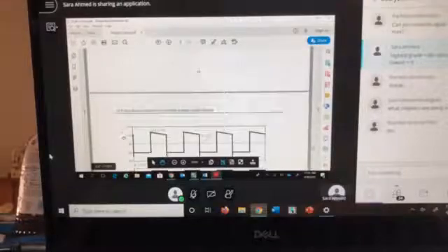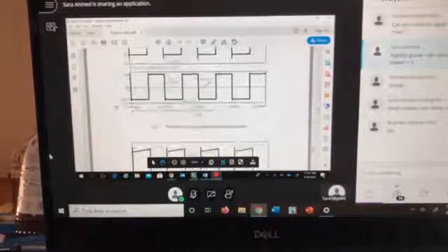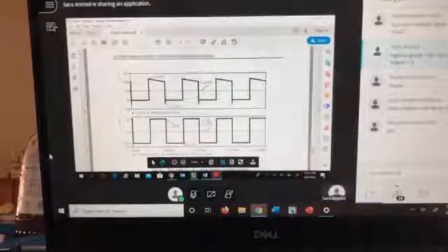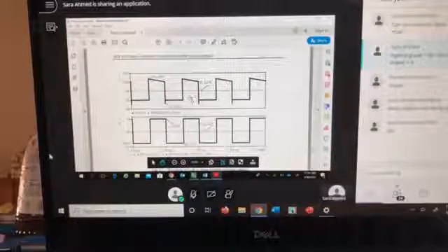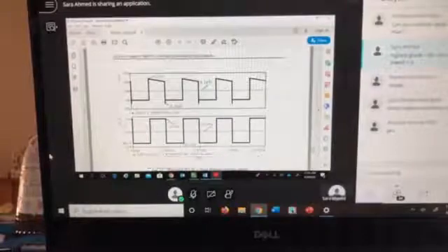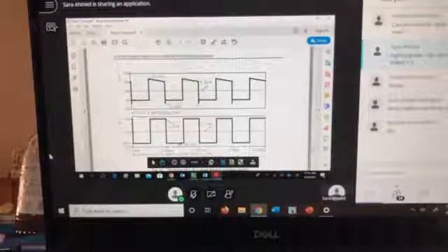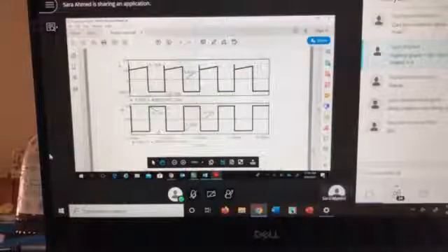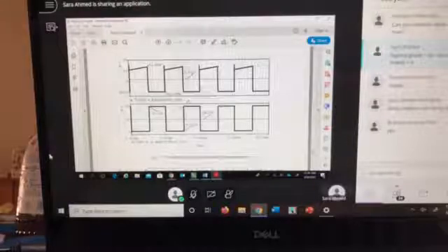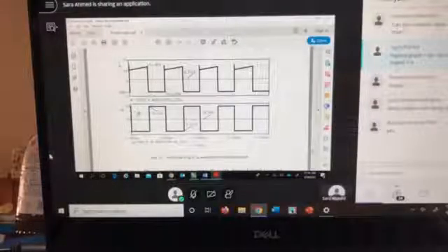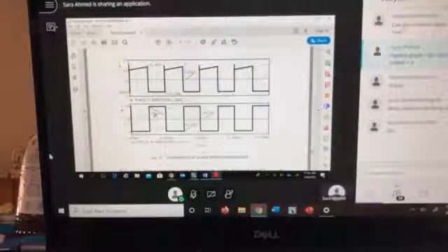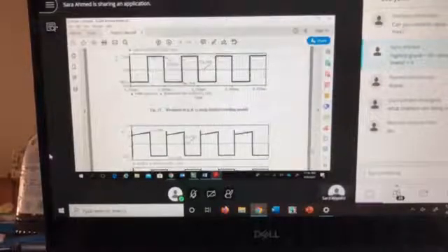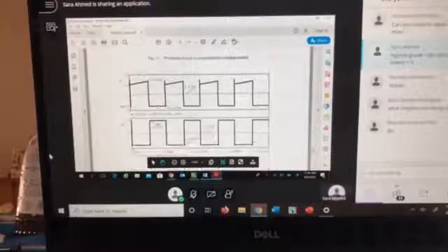And then we're asked for two more, which is IDVD and IMVM, which is the MOSFET and diode waveforms. So this is how they should look. Again, you can verify you're getting the right thing by having what? The diode voltage, we calculated for it, it's 0, and then it reaches here to 48. So this is what you should have, maximum and minimum. Same thing for the MOSFET, but the opposite. It's 0, and then it goes to the max, and then it goes back to 0 and up. So when the duty cycle is in D, then you're turning on your MOSFET. When it's D prime, you're turning on your diode. So you can see that they're opposite of each other. When the diode voltage is 0, then the MOSFET has the full voltage, and vice versa.